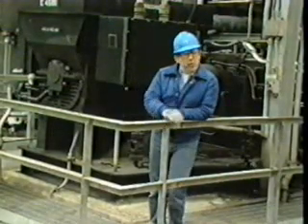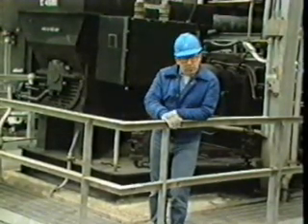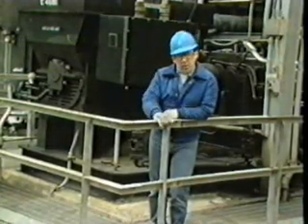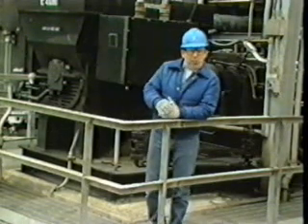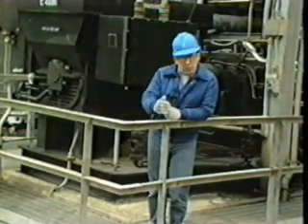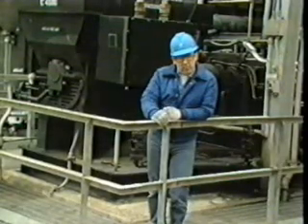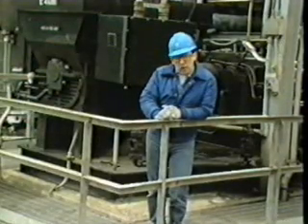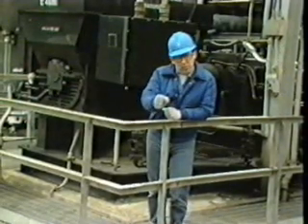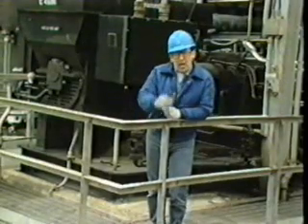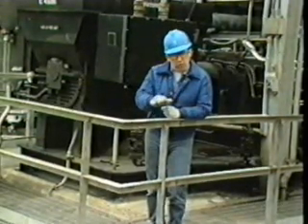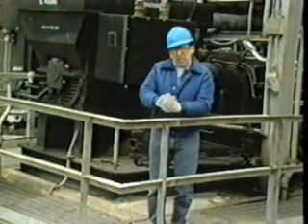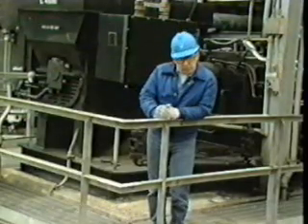Centrifugal compressors are available over a fairly wide range of speeds, anywhere from 3,000 RPM on up to as high as 50,000 RPM. Therefore, the type of power unit used depends on the desired speed range, loading of the compressor, and available fuel sources. In higher speed and load applications, the steam or gas turbine is the most commonly used. Now, in low-speed or small-load compressors, electric motors are sometimes used. Let's take a closer look at these different drivers.